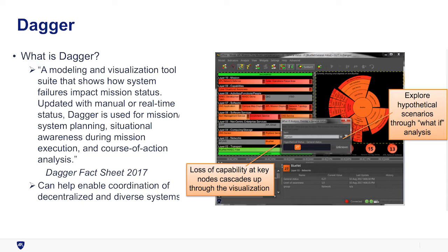And so what this tool allows you to do is apply what's called failure modes and effects analysis, which allows you to look for those single points of failure, allows you to think about how to get your redundancies just right, and allows you also to incorporate a probabilistic risk assessment and ultimately build the spacecraft that you need.